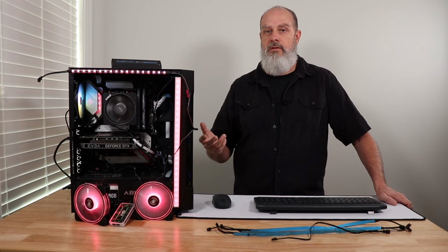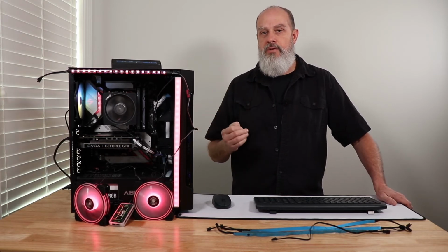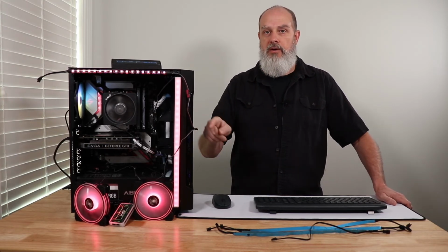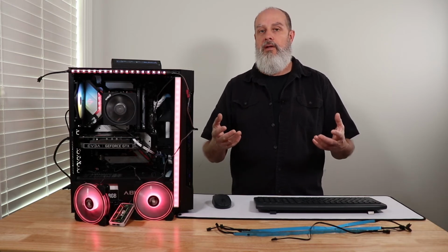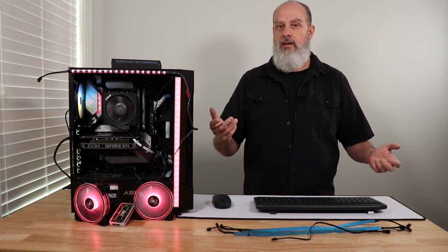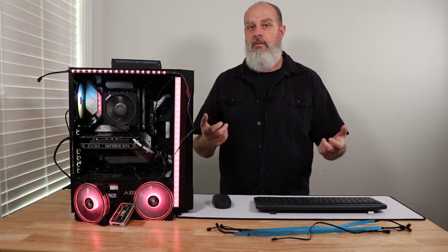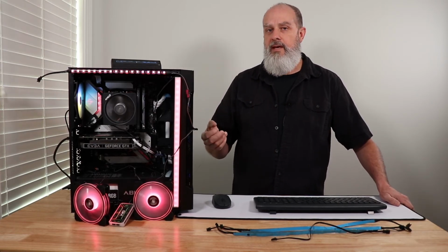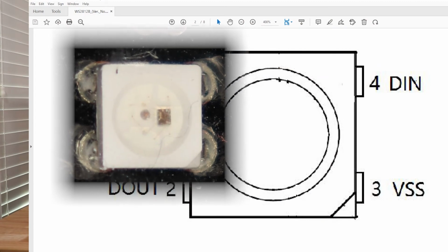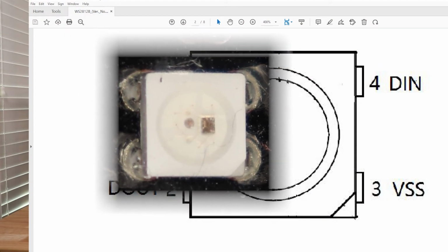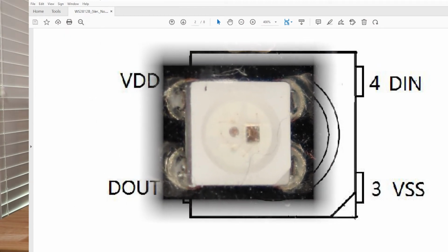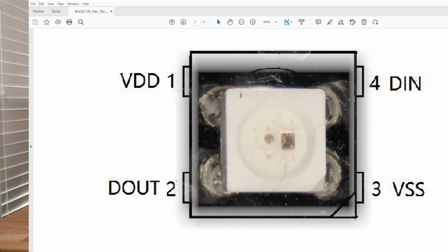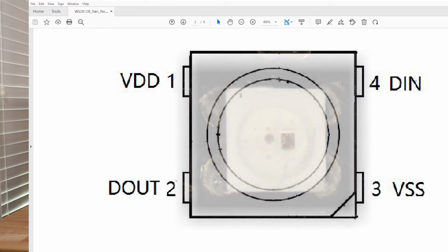Now, on most of these controllers, I can reduce that number down. As I go down into the strip, say there's 12 LEDs on a strip, and I tell it there's 8, it only lights up the first 8. But the real important piece to this is that each individual RGB LED has actually 4 connectors. We talked about this being a 3-pin, 5-volt, data and ground, but each RGB package itself has 4 connections.